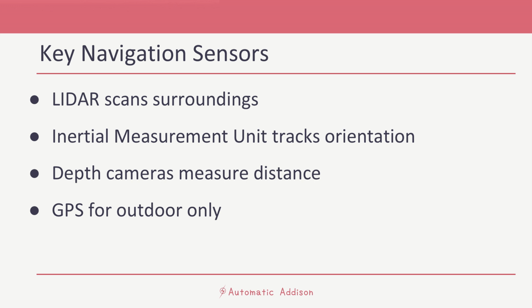For a real robot, instead of using simulated sensors, we would use real hardware. Fortunately, most of the popular IMUs, LiDARs, and depth cameras on the market have ROS2 publishers you can find on GitHub that will read the data from the sensor and publish that data to a ROS2 compatible format. These ROS2 publishers are also known as drivers.